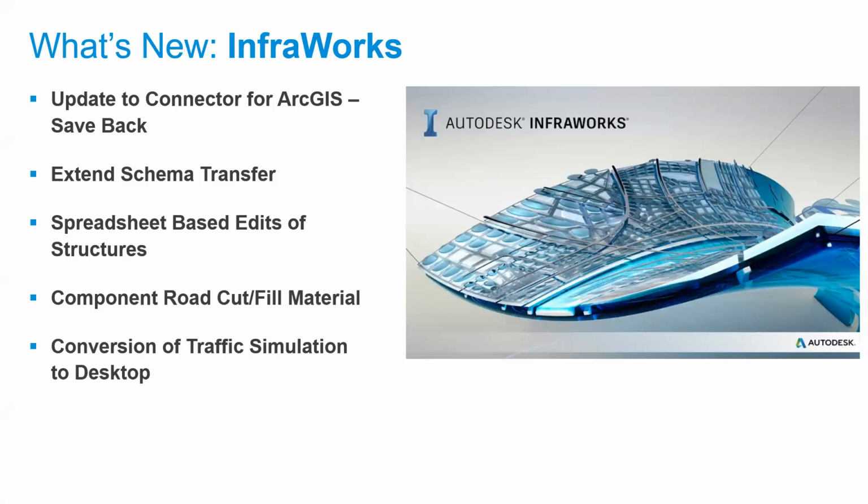Infraworks 2020 had a number of improvements, starting with the update in the ArcGIS connector, where previously you could only access GIS information from the ArcGIS connector, but now you can save back your GIS information, the one that you have maybe updated or worked on within Infraworks. You can update it back into your ArcGIS Online, or if you have access to ArcGIS Enterprise. The same also applies to the extension of the schema transfer, which is more or less similar to the saving back into the ArcGIS connector.